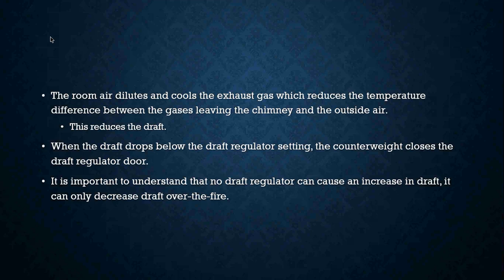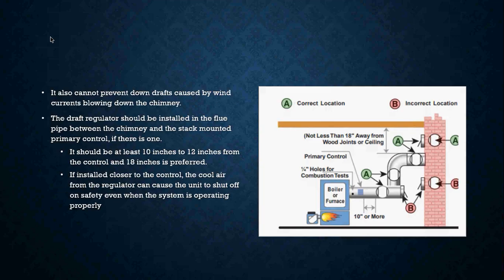Again, no draft regulator can cause an increase in draft. It can only decrease the draft over the fire. That's very, very important.